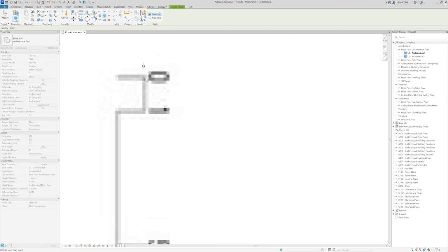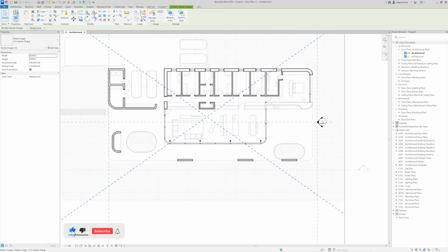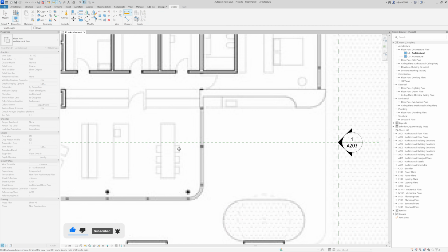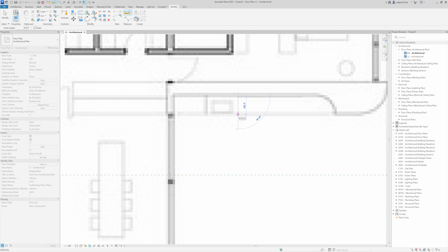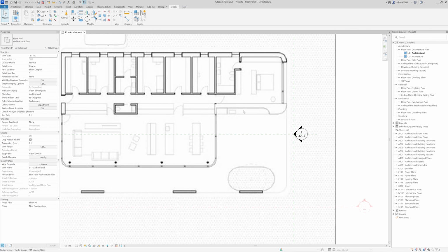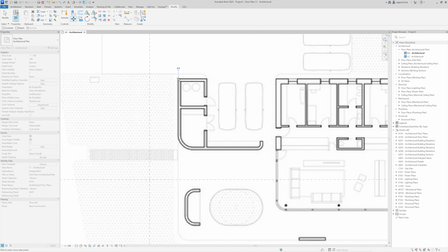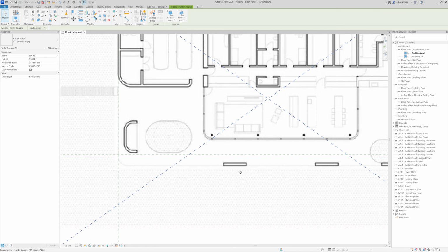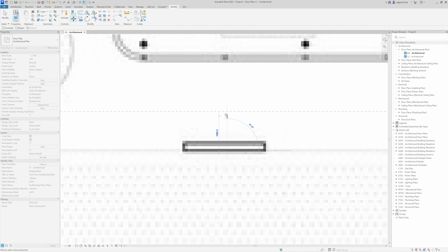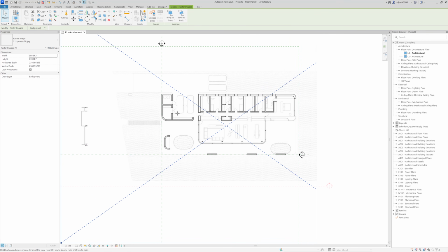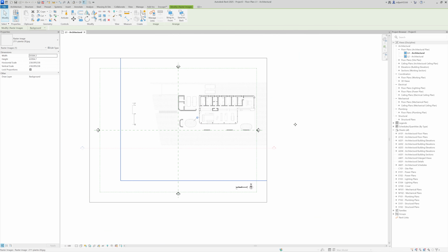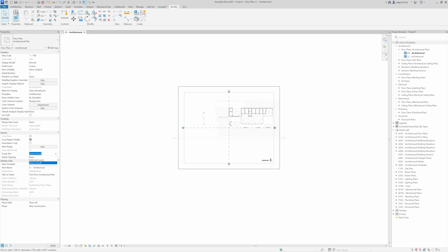So this part here to this part here becomes 1 meter. And I will just check some other things, like this one, so it looks like these dimensions are reasonable. So this is around 600 and this is fine. And what I'm going to do, I will place this wall to this reference plane and then those bottom walls to this one. So I'm going to use the reference planes we have in this template. Then I'm going to pin the image. PN is a shortcut. And what I don't want to have are those scope boxes and then crops.